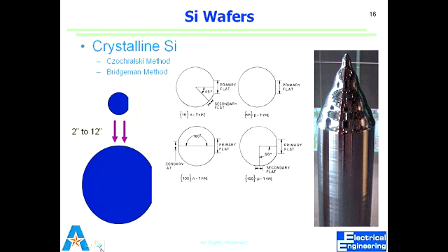So if I have a wafer which is N-type and it is 100, it will have two flats. One primary flat, also a major flat, the other a secondary flat, smaller flat. A flat is nothing but the side of the wafer is ground, right? Made plane. So everything else is perfectly circular. We put this. So these are for a 4-inch wafer. And this is now 16. We are making 16-inch wafers now.